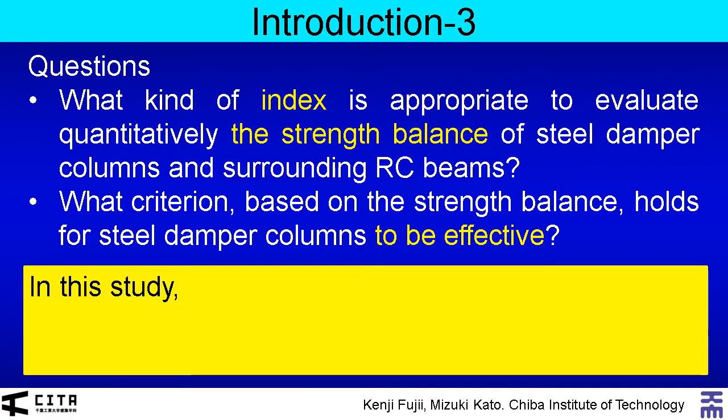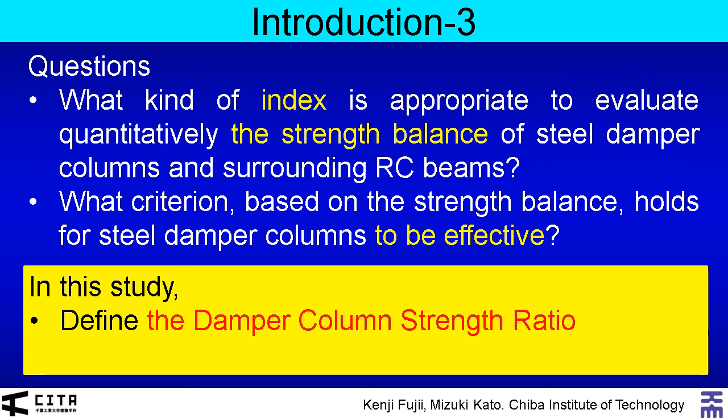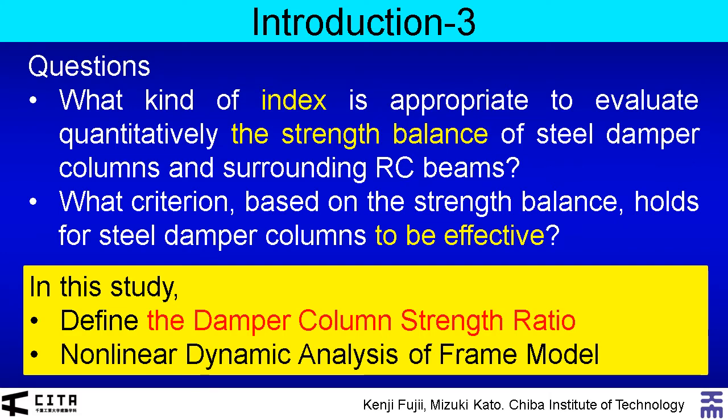So, in this study, we will define the damper column strength ratio based on the rigid perfectly plastic mechanical model. Next, a nonlinear dynamic analysis of frame model is conducted to investigate the influence of damper column strength ratio on the nonlinear seismic response of RC frames with steel damper columns.